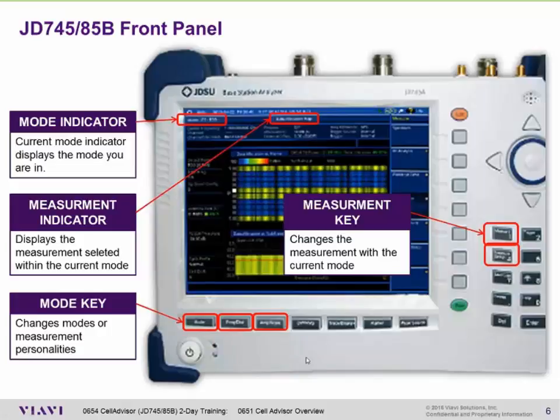The amplitude scale, I highlight that. I'd probably say that's one of my most favorite of all 5 buttons, in large part because with a test instrument, when it comes to dynamic range, it's through the amplitude scale that I turn on my preamp for weak signals, or I add attenuation, especially when I'm using a hardwired connection that may still be overdriving my instrument. It also serves to expand my scale so I can have greater visibility into what I'm seeing. So please make sure that you use the amplitude scale button as much as possible so that you have the greatest level of visibility.